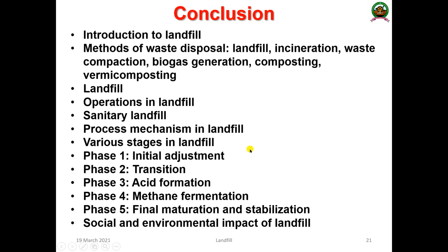What are the various stages in a landfill? Stage 1, the initial adjustment. Stage 2, the transition. Stage 3, the acid formation. Stage 4, the methane fermentation. And stage 5, the final maturation and stabilization. So there are various phases and stages. Finally, what are the social and environmental impacts of this particular waste management method, landfill?